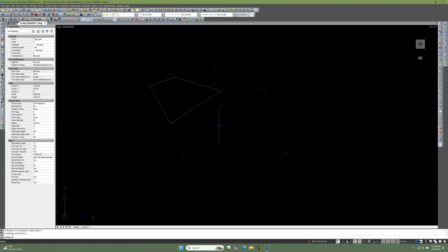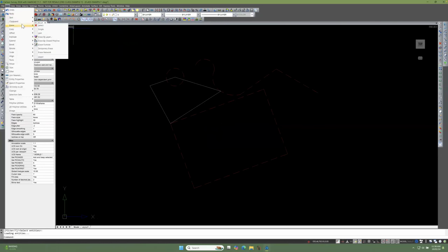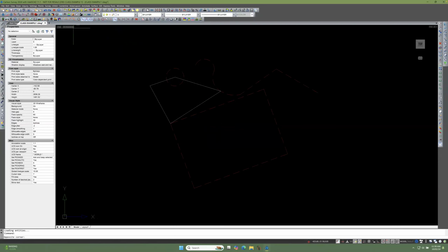And we've already started a drawing. We might as well just stay in this drawing. We'll use it, but we need to get rid of everything that we've drawn. Now, you could select it and choose the erase command from the edit menu. You can select it and hit the delete key on the keyboard, or you can choose the erase select command, or you can even type down at the command line at the bottom of the screen, erase or delete.